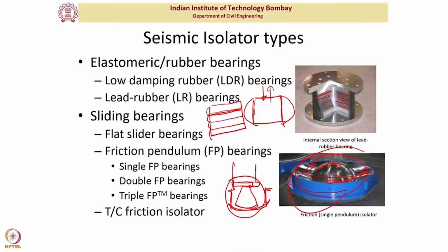And coming to the issue of neoprene longevity, basically what happens, neoprene is a synthetic rubber. Now, after 10-15 years, you have to keep inspecting these neoprene bearings to see that they are still providing adequate performance. Otherwise, you need to replace them. In isolation, we are now moving towards natural rubber bearings.